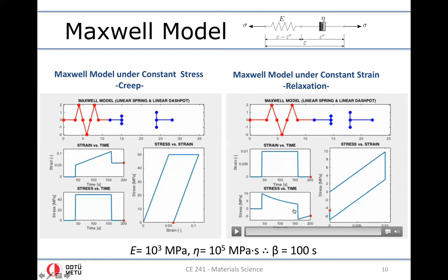Okay, and after about 100 seconds, which corresponds to t equals 140 seconds, about 63% of the stress has decreased. So that means the stress corresponding to t equals 140 must be something like 33.7 megapascals. So they are all observed here.